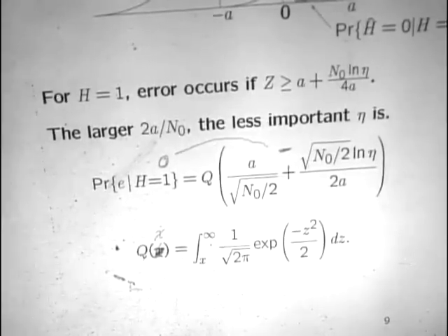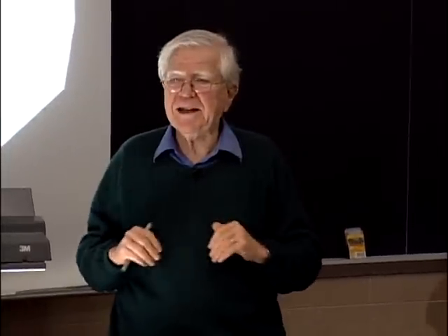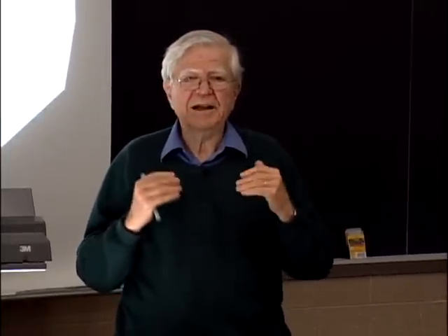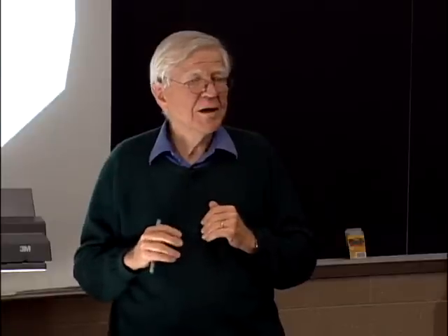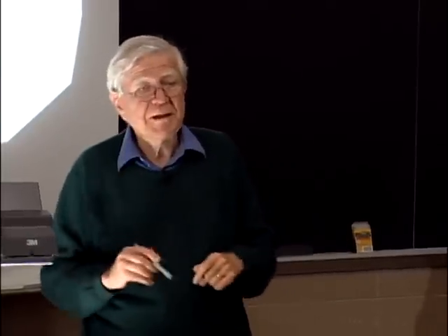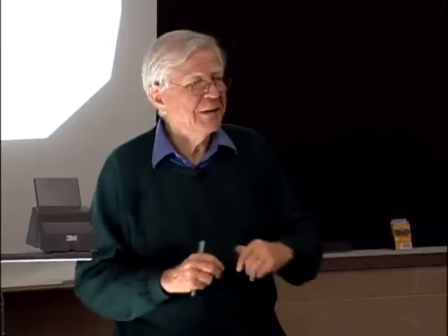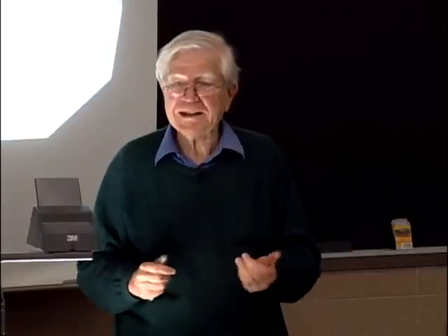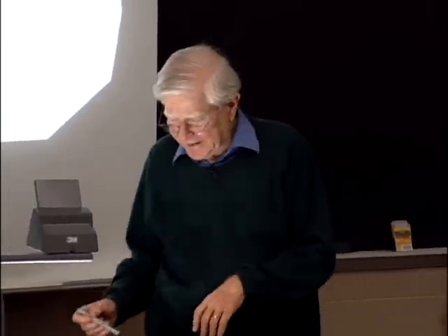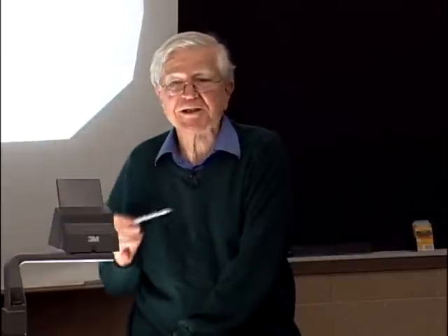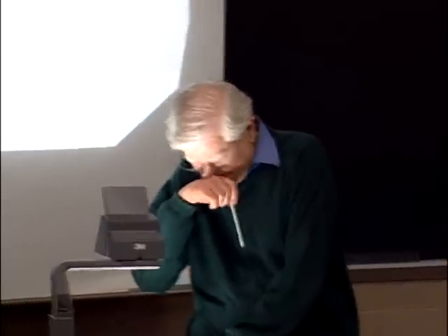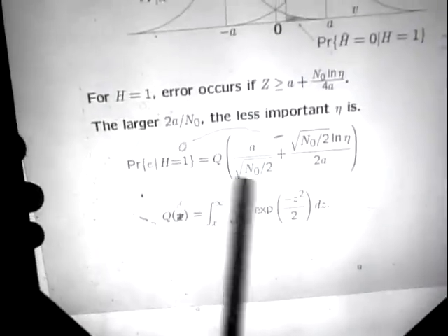I mean, you scale the data in whatever way you please, and when we've gone from baseband to passband, we in fact have multiplied the energy in the input by a factor of 2, and therefore, because of that, n0 at passband is going to be square root of 2 bigger than it is at baseband. Don't like that? Live with it. It's the way it is. Nobody will change n0, no matter who wants them to change it. Okay, so this term makes sense.